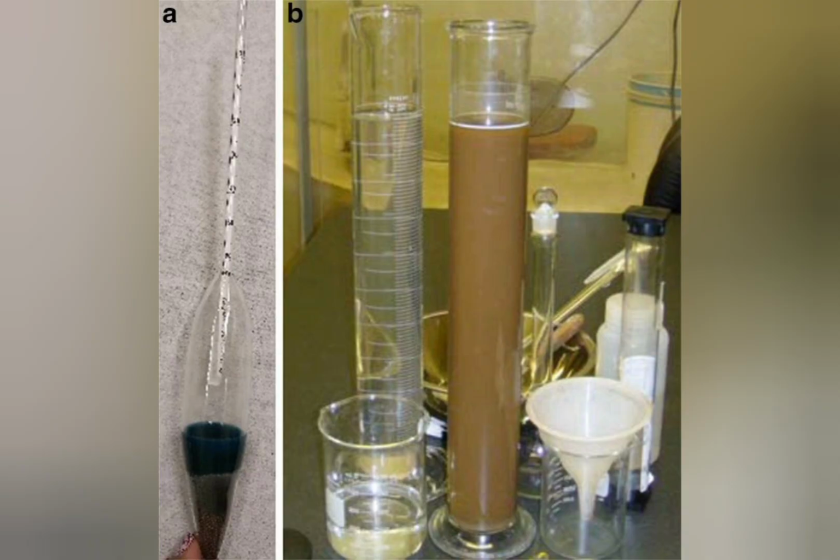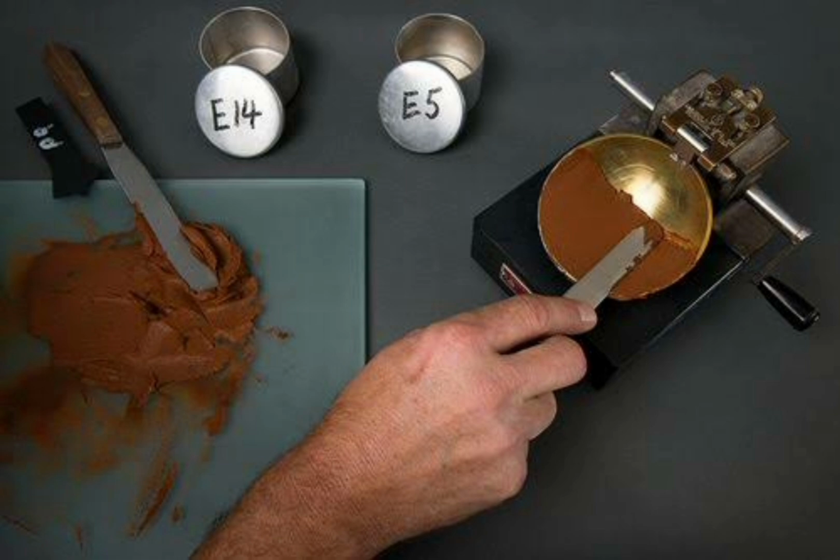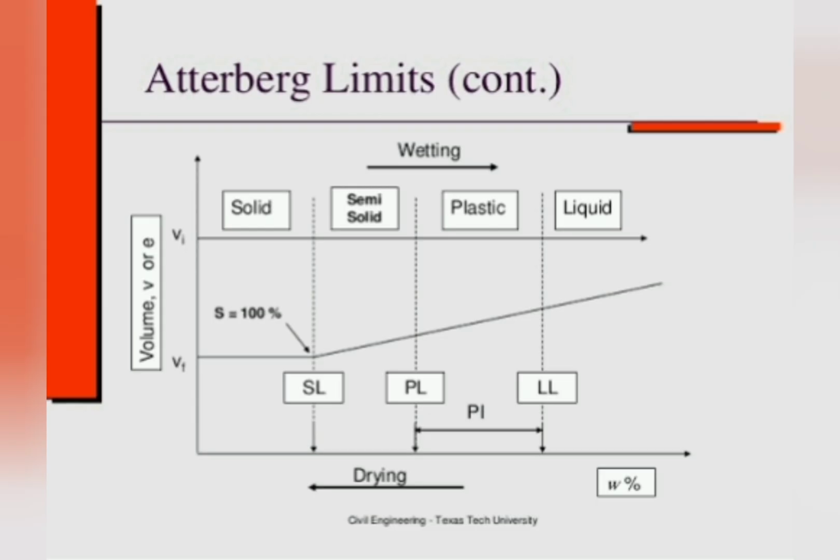The next critical classification test, absolutely vital for understanding fine-grained soils, is the Atterberg limits test. This test, developed by Atterberg, identifies the water content at which a soil changes between three critical states: solid, plastic, and liquid. The liquid limit, LL, is the water content at which a soil behaves as a liquid. A small groove in a soil pat will close over a distance of 13 millimeters after 25 blows from a standard cup. The plastic limit, PL, is the water content at which the soil can no longer be rolled into a 3 millimeter thread without crumbling.